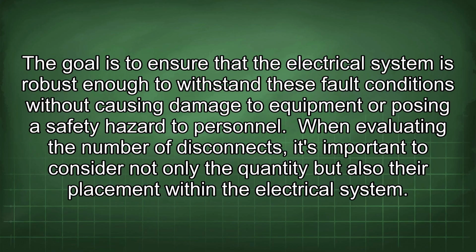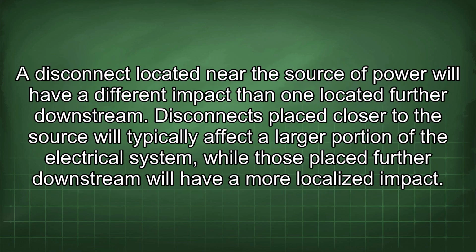When evaluating the number of disconnects, it's important to consider not only the quantity but also their placement within the electrical system. A disconnect located near the source of power will have a different impact than one located further downstream. Disconnects placed closer to the source will typically affect a larger portion of the electrical system, while those placed further downstream will have a more localized impact.